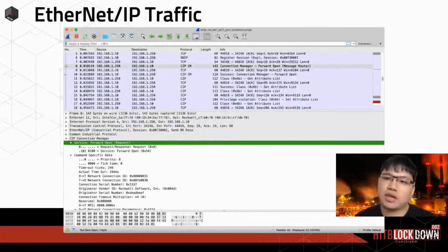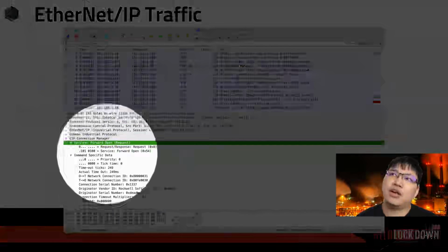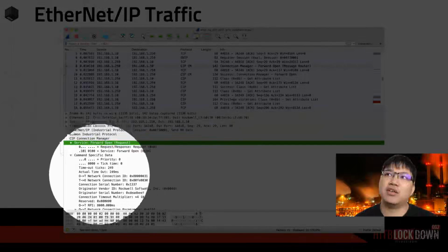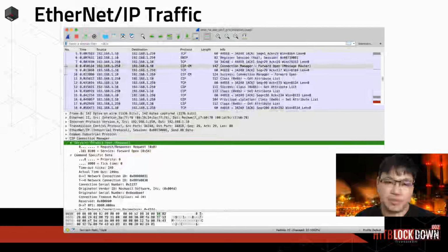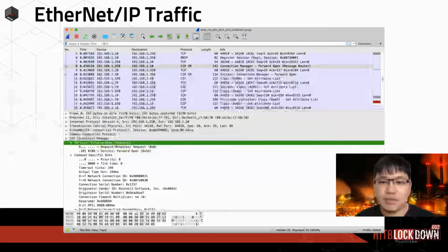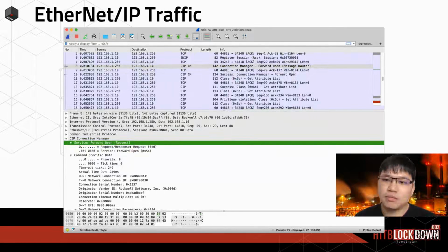Here in this picture, you can see the communication of CIP connection managers, which is more complicated than Modbus, with many headers, network connection, original vendor, serial number, and many attributes well used in EtherNet/IP CIP traffic. But of course, it is necessary to know clearly what the fields represent before performing an attack. As a hacker, you need to know which field, which content, which byte, you can use to make an impact with these protocols. So you need to first know this.